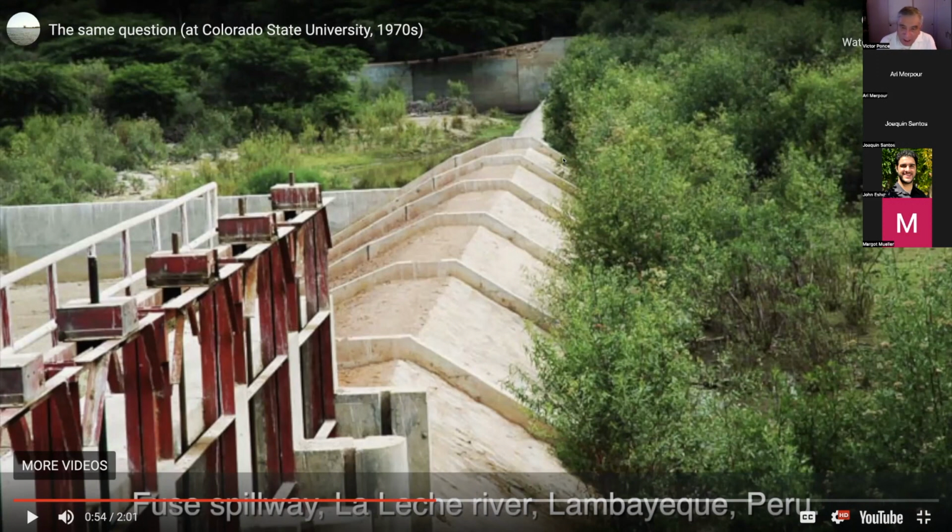So over here, if and when it happens, it has not happened yet, and I believe this is still there as far as I know, but when the water flows over this level, it'll destroy the spillway and open up the spillway to 2 to 3 times its capacity. In other words, the flow would now be free to flow in here, which was not possible while the spillway was there. This is typically a solution. We have seen solutions of this type in many places, fuses.